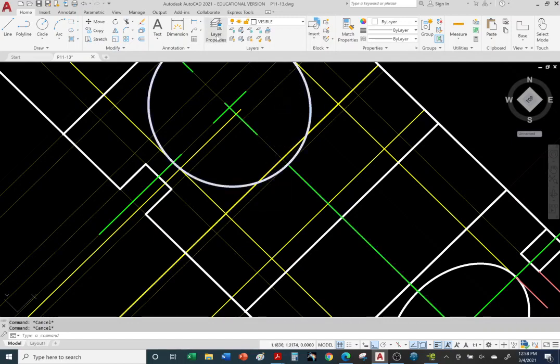All right, so let's go ahead and draw an ellipse. Once again, ellipse. And here is the center point. Let me turn on Object Snap. Oh, it's already on. Okay, so I'm going to click. And then I'm going to go and define one of our diameters for the ellipse. I'm going to click at this intersection between the thick yellow construction lines. Click, and now you can see it.